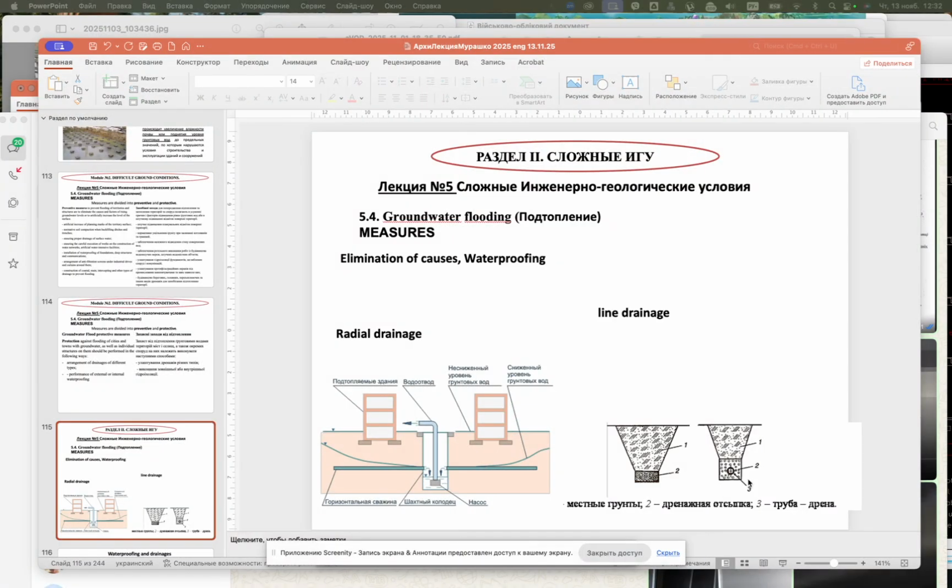And also, the geotextile, it's like a fabric with small openings which can let the water inside of the pipe, but protect the pipe from the ingress of small particles of soil. So gravel, pipe, and here we can use something like sand or something which can filtrate the water really well.